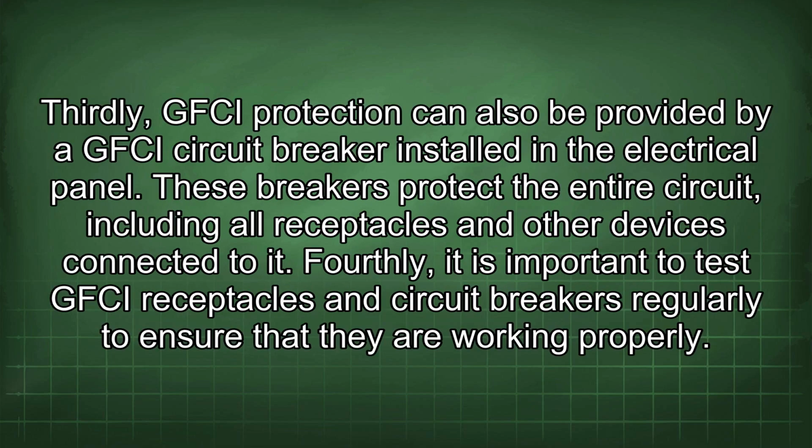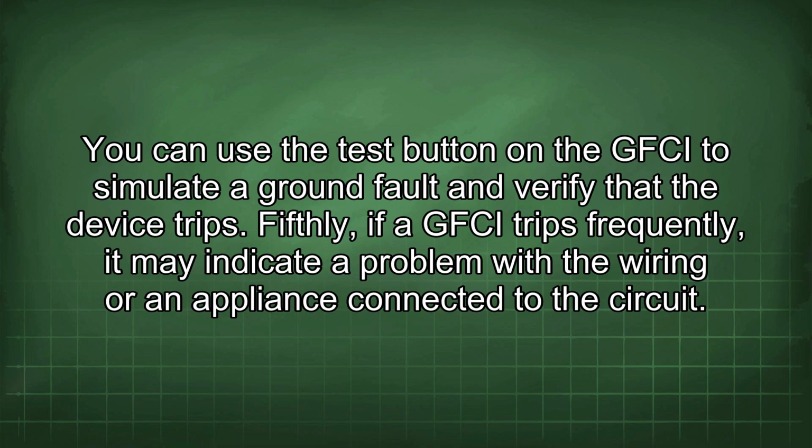Thirdly, GFCI protection can also be provided by a GFCI circuit breaker installed in the electrical panel. These breakers protect the entire circuit, including all receptacles and other devices connected to it. Fourthly, it is important to test GFCI receptacles and circuit breakers regularly to ensure that they are working properly. You can use the test button on the GFCI to simulate a ground fault and verify that the device trips.